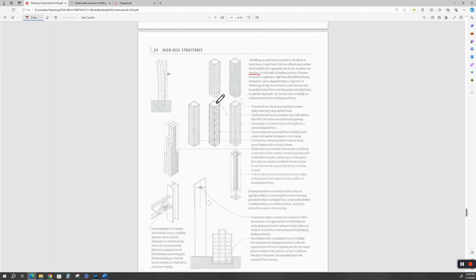Yeah, because the outer skin has to be structural. And a frame tube is closely spaced, which was like the World Trade Centers. They called them bundled tube concepts back then. The columns that went all the way up were rigid, and they were really close together. And so they worked like a stack of straws. And it worked real well, unless you fly planes into them. But that's why it collapsed the way it did.